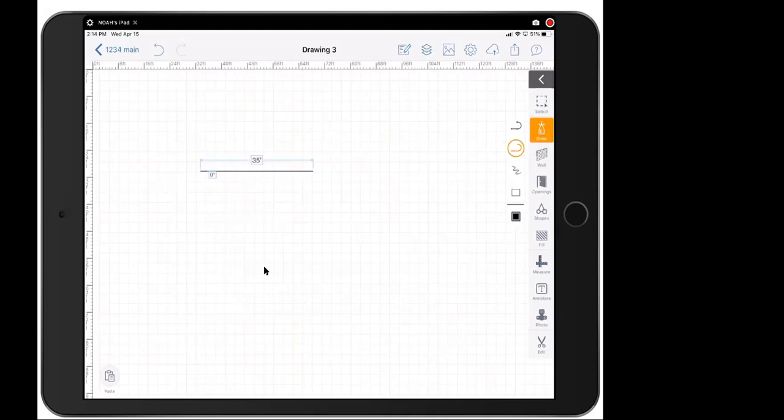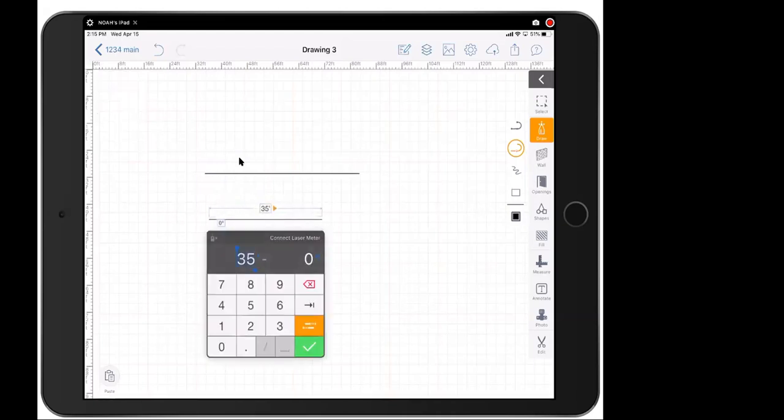So if you're a contractor, let's say, and you are drawing up a floor plan or maybe a proposed scope of work, what you first want to do is take the measurements, actually with your measuring tape or measure wheel, draw a line, and then you can tap on this dimension to input what the actual dimension is. And it's very useful because sometimes drawing these lines with your finger, you can't always get it exactly where you want. So being able to tap there and change the distance just by manual input is pretty important.